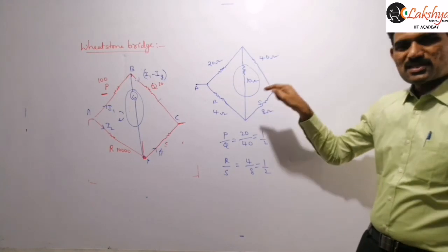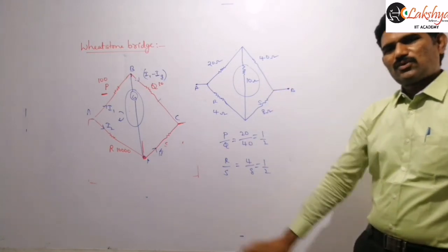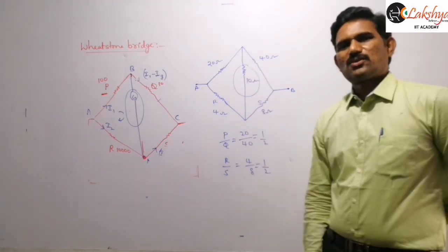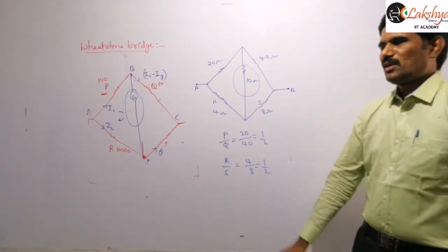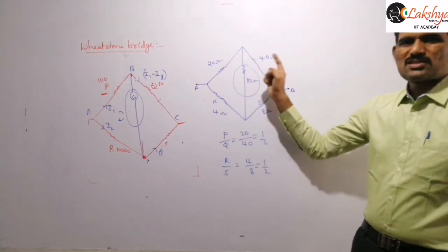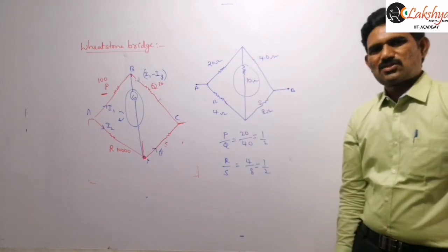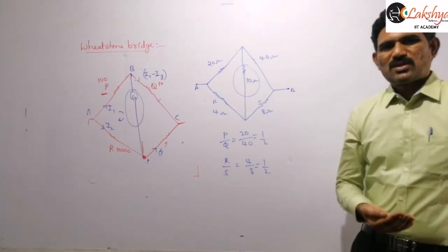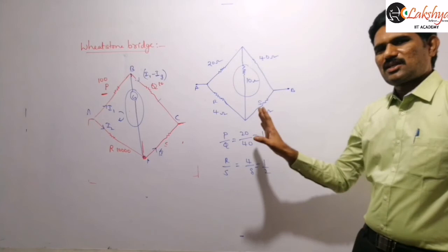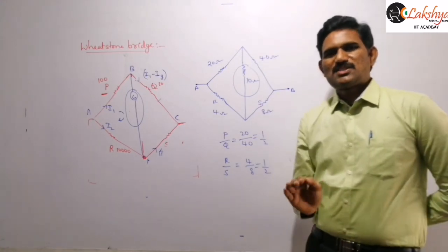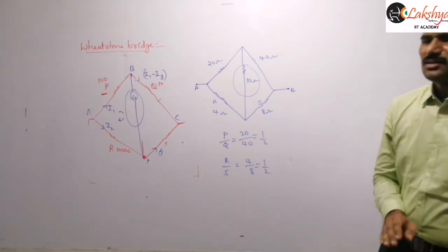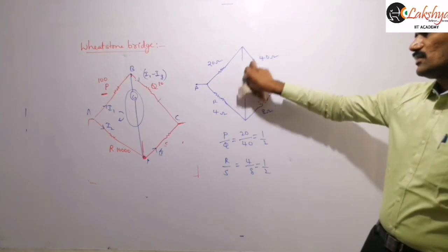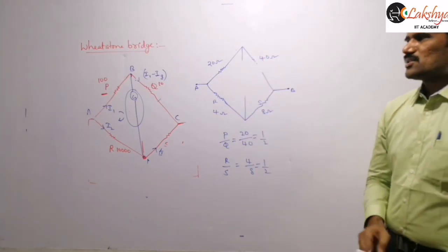But if that resistance is present, and if we don't know the balanced Wheatstone bridge condition, and I ask you to find the effective resistance, then you can't say directly that these two are in series, because in the middle one more resistance is connected there. So that is the advantage of this Wheatstone bridge. By knowing the balanced condition, whenever such an arrangement is there, you can first verify whether the bridge is balanced or not. If it is balanced, then we can remove this resistance here, right, then the circuit will be easy.